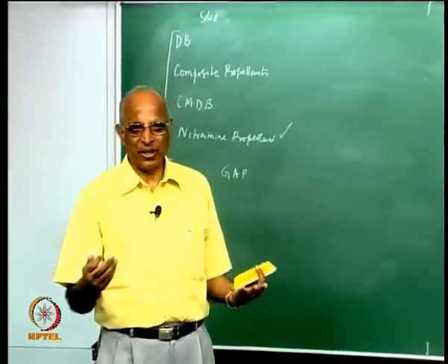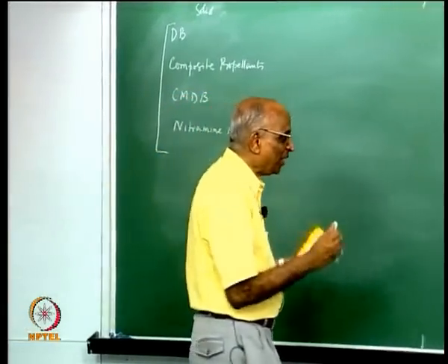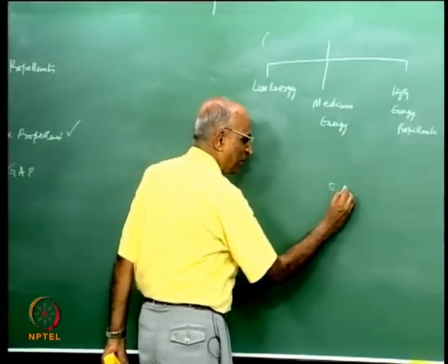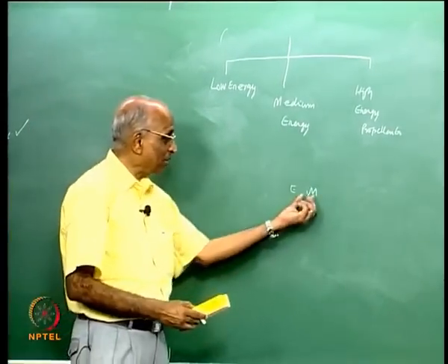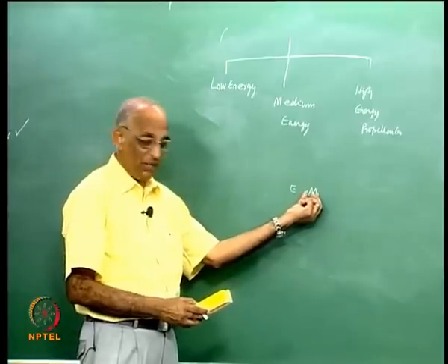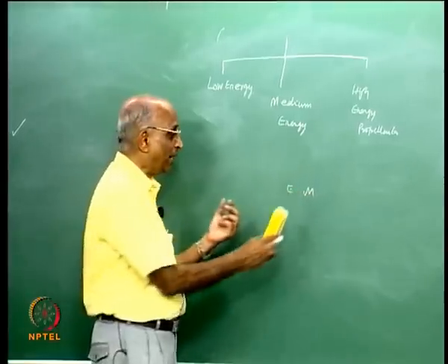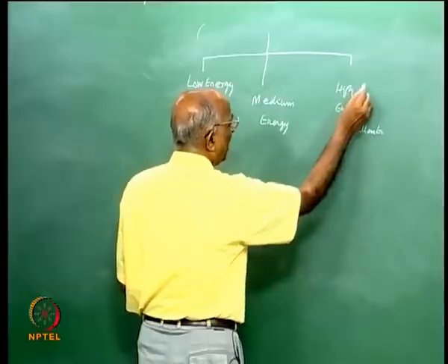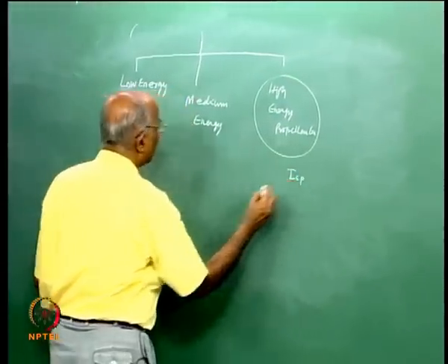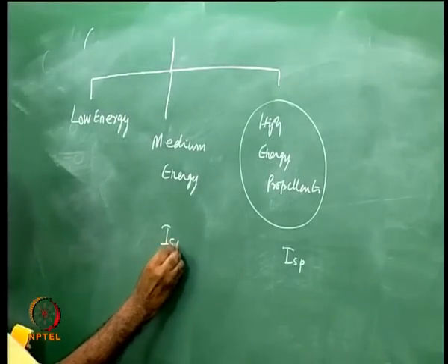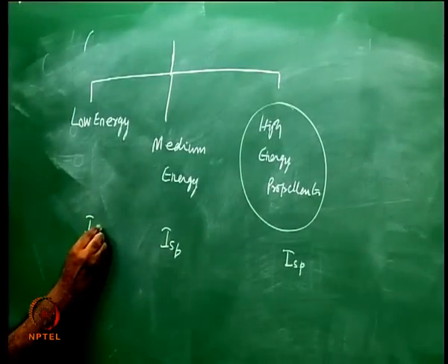Energy is a misnomer in rocketry, because it is not only energy which is important, but a low molecular mass is also important. Therefore we told ourselves hydrogen oxygen has a low molecular mass, even though the energy may not be high, and therefore when we say high energy propellants, we always mean high ISP propellants, medium ISP propellants, and low ISP propellants.